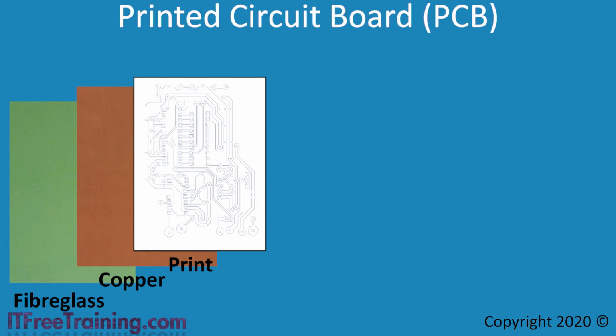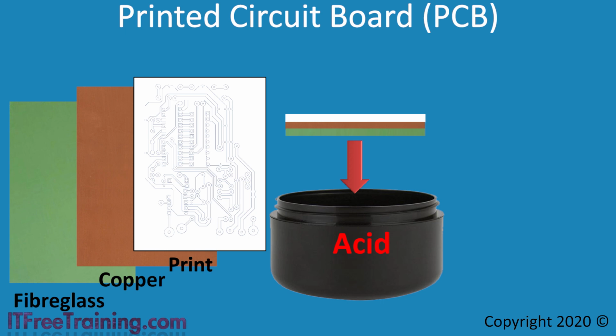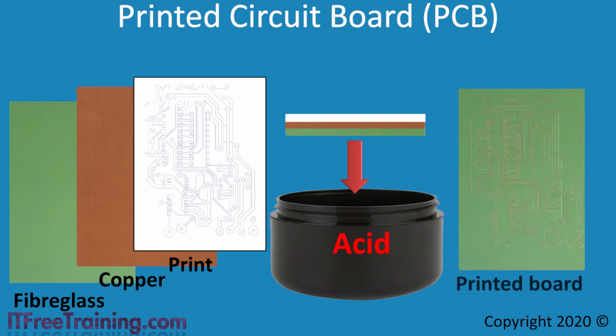Historically, the next step was to place the PCB in acid, but nowadays photoresistant materials are used, so the PCB would simply be exposed to light, most likely ultraviolet light. The result is the same. The process will remove extra copper, leaving essentially wire-like tracks on the PCB, and these are referred to as traces.